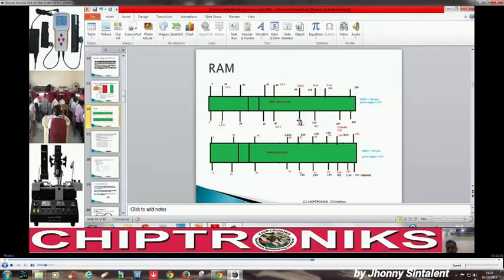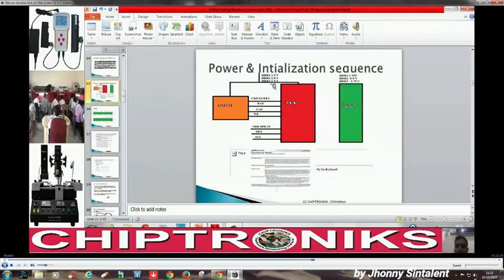You can get this printed out and you can measure, whereas you should be only concerned about 3 supply voltages. Those are very specific, very important: 2.5 volt for DDR1, 1.35 termination voltage; 1.8 volt is the DRAM voltage, 0.9 termination voltage; 1.5 is for DDR3, 0.75 is termination voltage, and we have to check other reference voltages also.